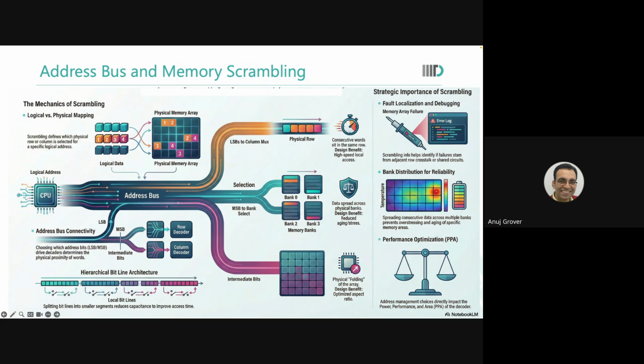This verification is not done at a typical schematic level, but this verification is done after the LVS has been cleaned. So your layout is ready. And after the layout is ready, means the physical locations of every bit are now established. This verification is done at that point of time.